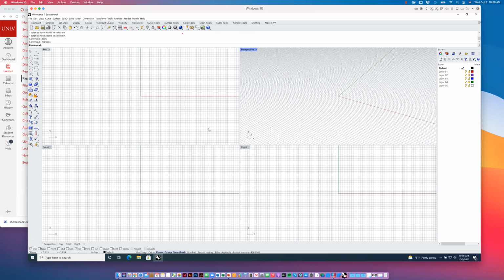That's really important because we're going to be making this stuff out of chipboard. We're going to be very precise about material thickness and making sure things fit inside the laser cutter, right? And that each of these are the same size and scale. And so making sure those units are set to inches is really, really important.